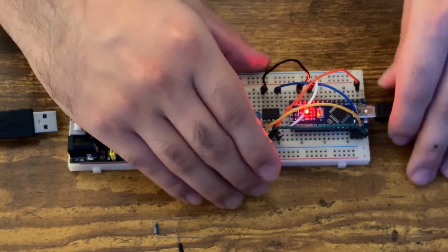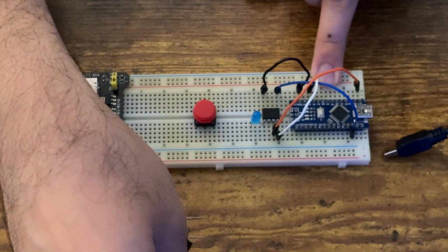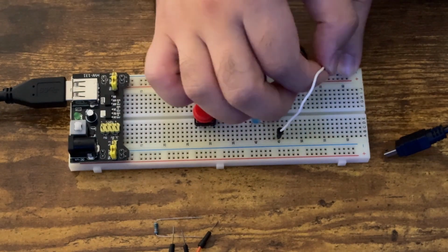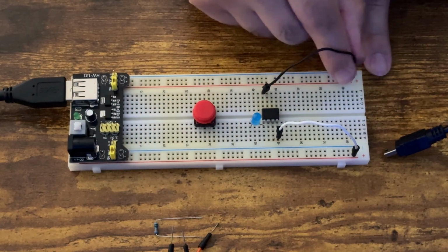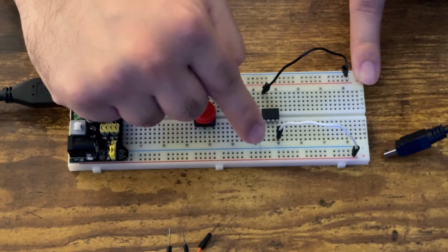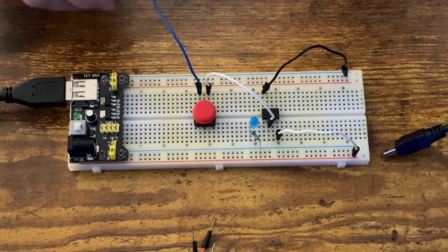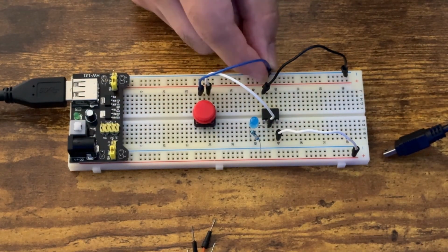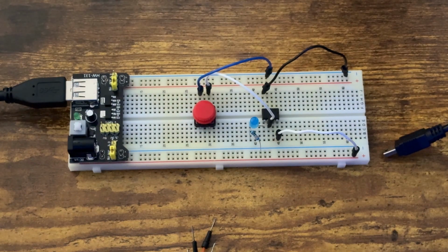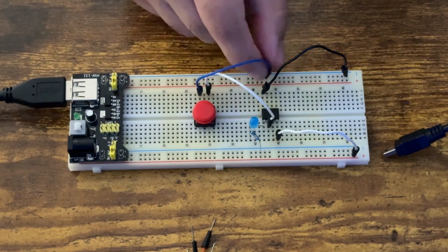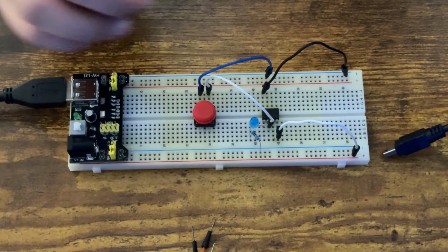So again, let's unplug Arduino. We don't need it anymore. Unplug connections, remove Arduino itself. So now what we want to do is, of course, connect our power to these power rails. So plus, minus here, and LED, same thing to ground through resistor, but our button will go to the next pin. And another pin, leg of button, goes to, actually where does it go, let me check. Okay, so ChatGPT says to ground. Okay, if it says so, let's check. So now we just need to power it and see what will happen.